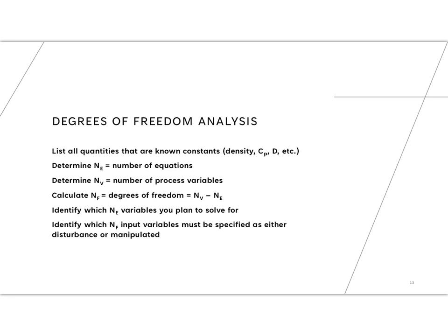So first, figure out the number of equations, okay, that's how many variables you can solve for. So look at the number of equations. If it was 3, then you can solve for 3 of your variables. Figure out which 3 those are going to be. Now, I'm going to recommend that it's probably the ones that you have listed in your derivatives, the d dt portion of a dynamic balance. Okay, so that took care of some of them, but now you have the n sub f number, the extra variables you have. And so now you need to figure out how you can specify those.